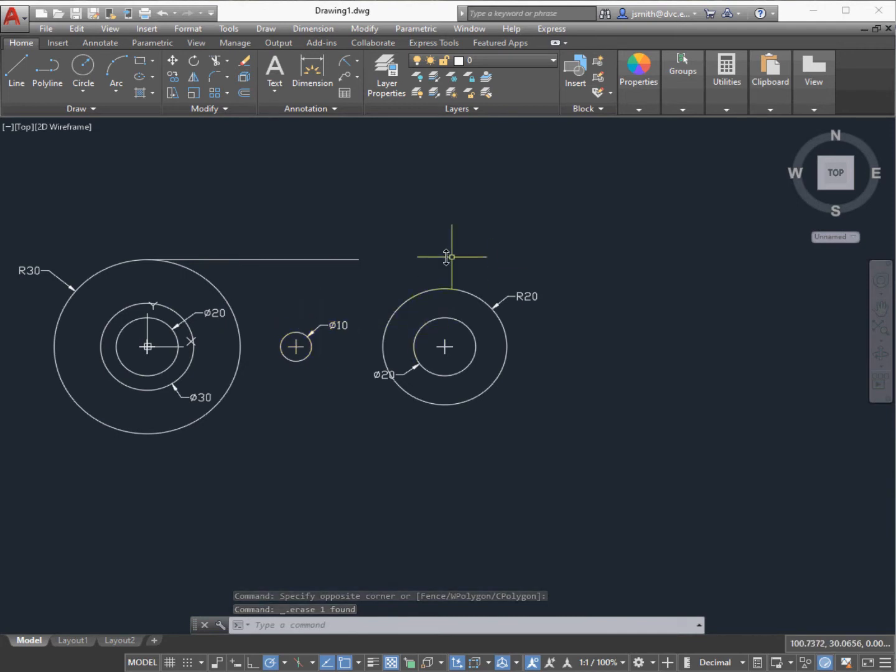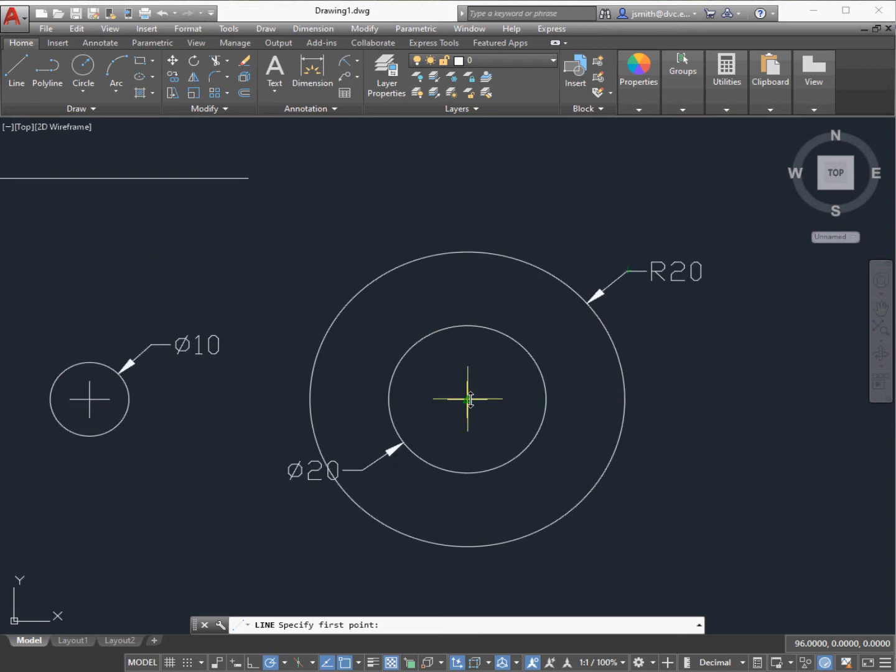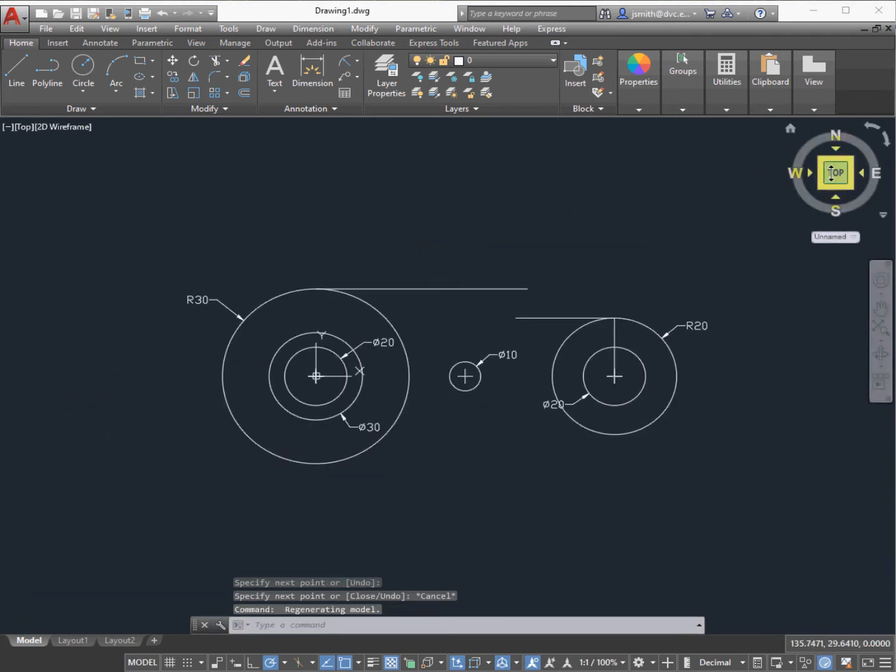That's more of a working line. So let's go ahead and do the circle that's coming from right to left, that line. So I'll go up from the start, hit the top of the circle, and then move my mouse to the left. And they're just going to overlap a little bit. Hit escape, and you'll see what's going on here so far.